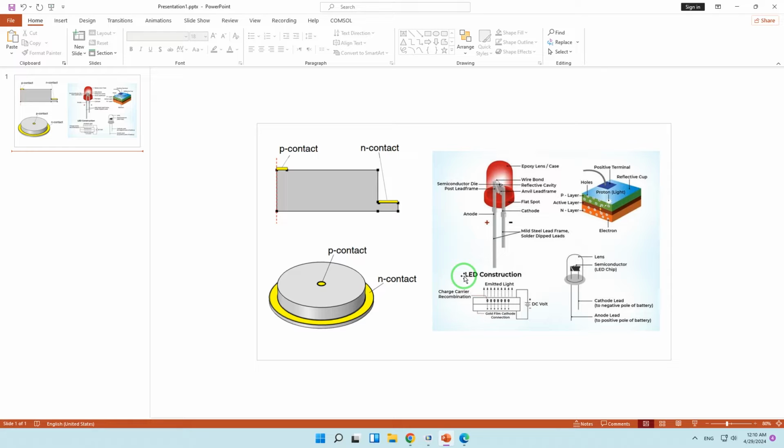And a rectangular trench has been etched down to the N-type layer at the right-hand side of the domain to allow an electrical contact to be deposited onto the N-type side of the PN junction, creating a ring of metal around the edge of the device. And then the P-type contact is deposited directly on the top surface in the center of this chip.